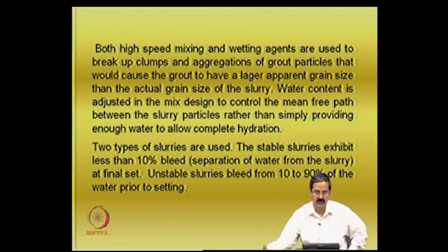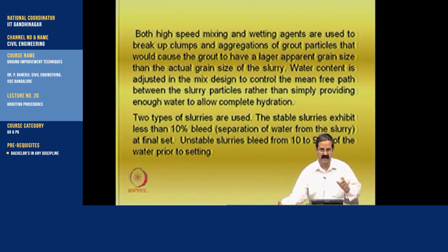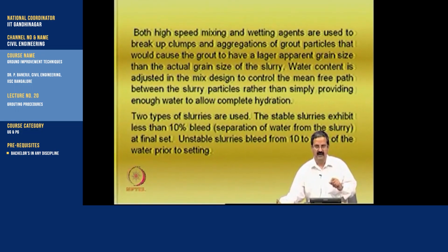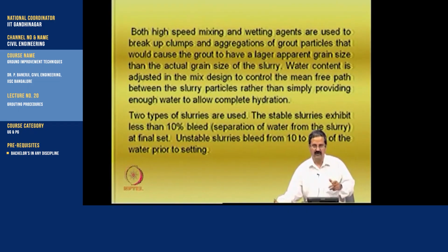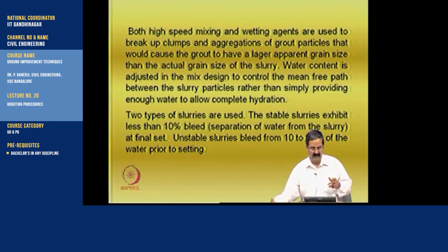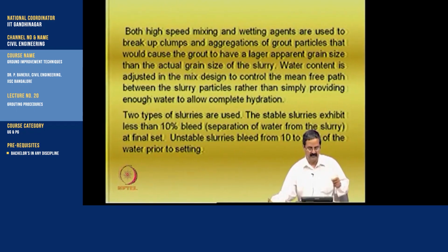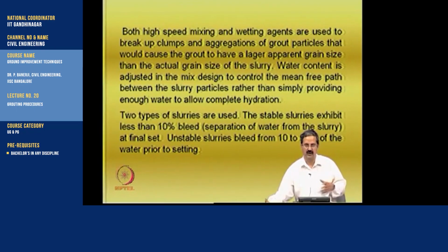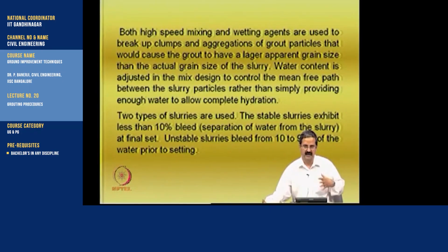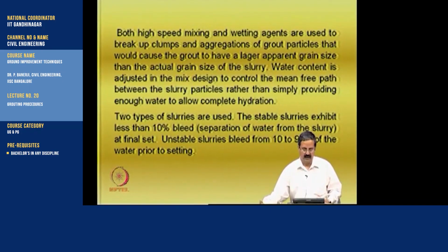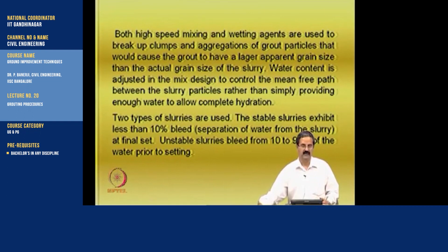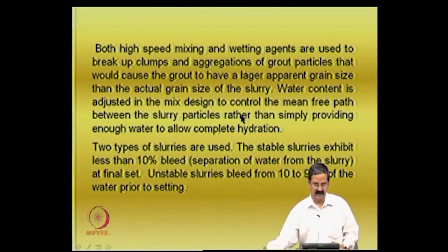In the case of cement mortars, the water cement ratio is somewhat critical, and we have a lower ratio, but here the objective is to have a lot of water available so that the mean free path is somewhat higher, there is water movement everywhere, and there is flowability also, compared to what you see in other cases.